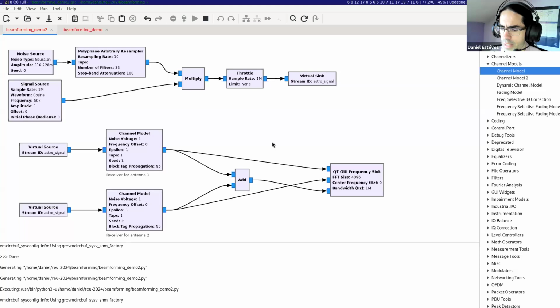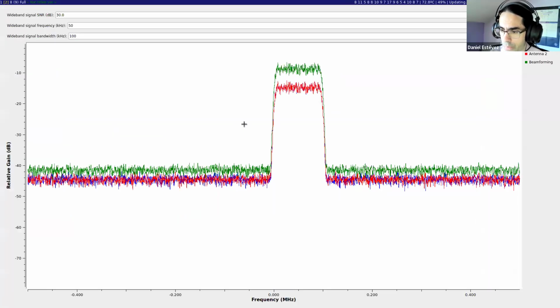The mathematical reason behind this is basically variance. So the power of a random signal is the same as the variance, and the variance of two random variables which are uncorrelated is the sum of variances. So that's the mathematical detail behind this. But intuition, if you have two uncorrelated signals, then the power adds. If the signals are correlated, such as here for this astronomical source signal, which is the same signal arriving to both antennas, then the power doesn't add. What adds is the amplitude. And so we get an increase by 4 in the power.